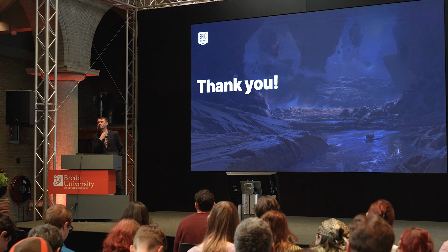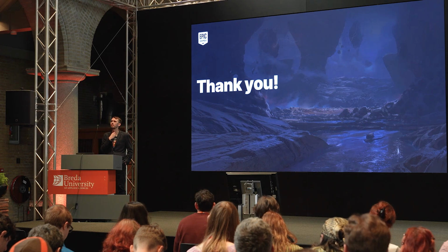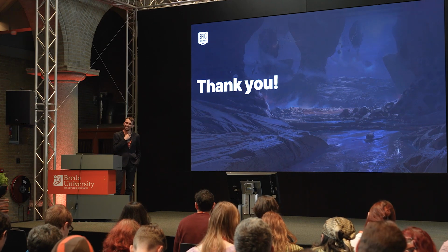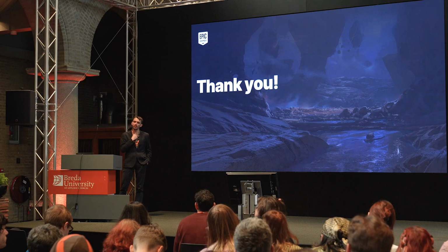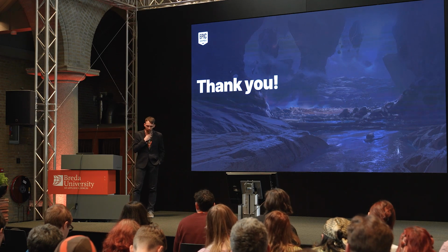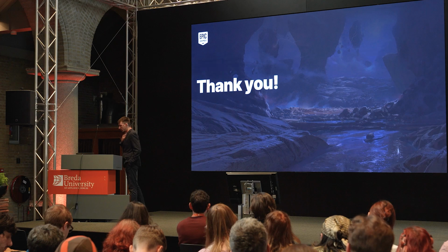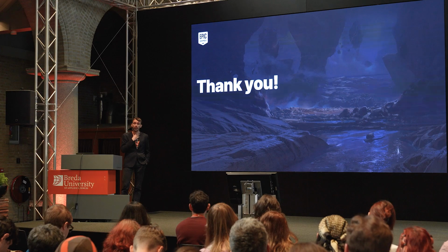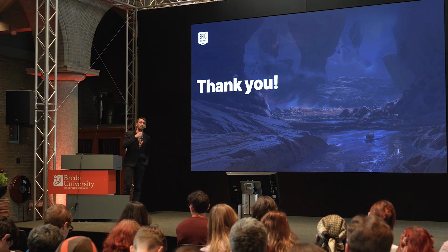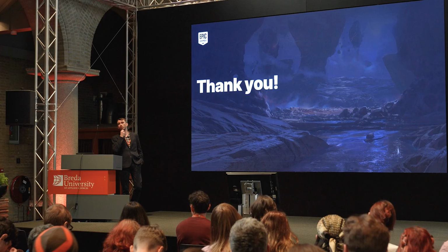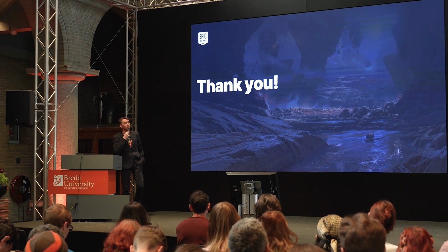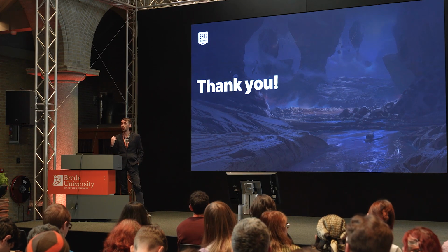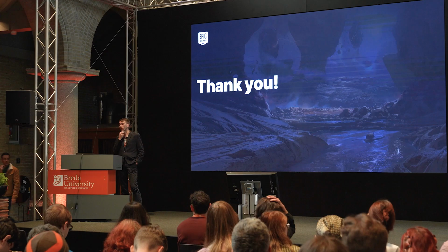Okay, and for vertex color and custom primitive data, can you pass that through PCG? Okay, so yeah, you can. We have support for custom instance data per instance on the ISM, the instanced static mesh component. Unfortunately, we don't have custom primitive data per component right now, so you need to push it to every instance. But we plan to have support also for custom instance data. And for vertex color, I don't think we can push it directly right now, but you can read from it with the mesh sampler.